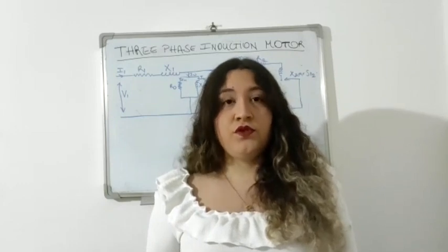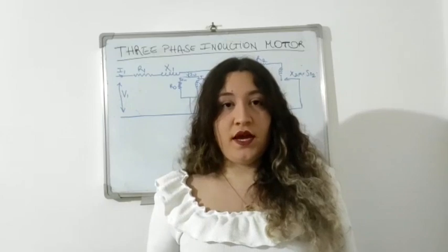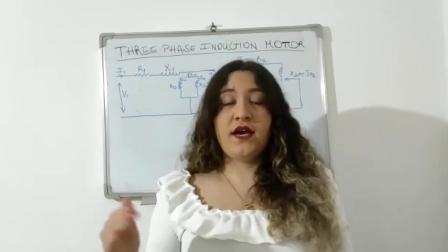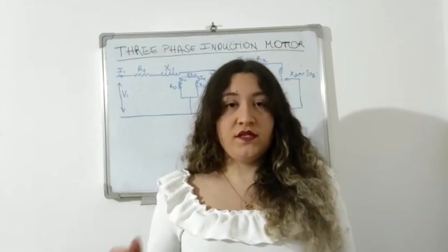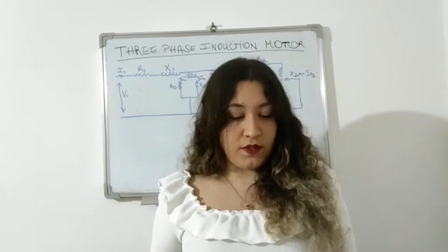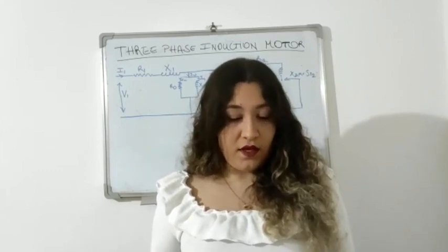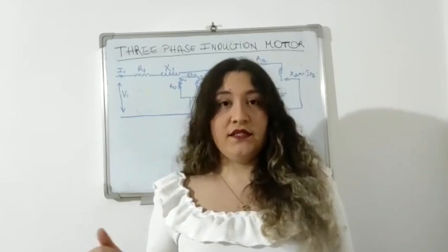An induction motor is essentially called a rotating transformer, where the stator acts as the primary and the rotor acts as the secondary. The energy transfer between the stator and rotor of an induction motor takes place entirely by induction, with the help of flux mutually linking the two.